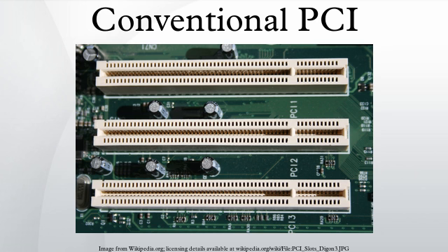These have one locating notch in the card. Version 2.0 of the PCI standard introduced 3.3V slots, physically distinguished by a flipped physical connector to prevent accidental insertion of 5V cards. Universal cards, which can operate on either voltage, have two notches. Version 2.1 of the PCI standard introduced optional 66 MHz operation.